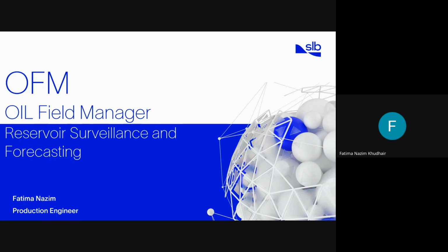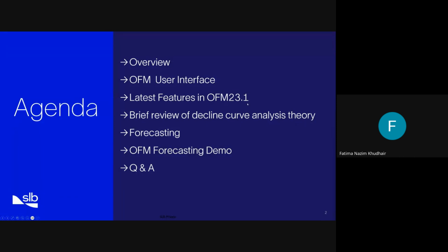Our presentation for today is going to be about OFM, Oil Field Manager. Specifically, the topic is reservoir surveillance and forecasting. Our agenda for today: we're going to have an overview about OFM, and I'm going to take you on a walkthrough of the OFM user interface. We're going to talk a little about the latest features that were added in the OFM 2023 version, and a brief review of decline curve analysis, the theory behind it, and why it's used. And of course, our main topic for tonight, which is forecasting. We're going to talk about forecasting in OFM, and we're going to move to the live demo in OFM, and the closing will be with the Q&A.